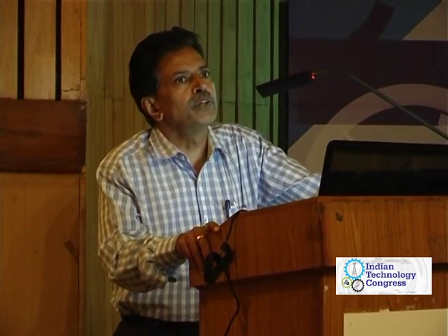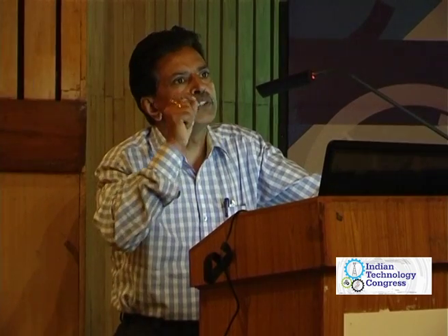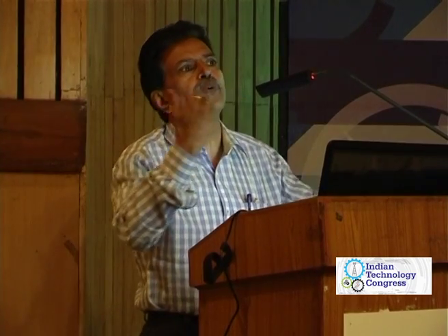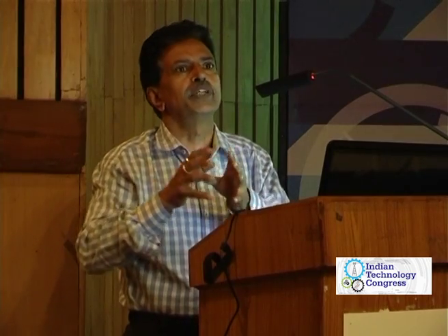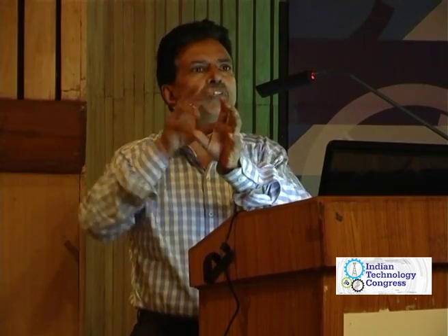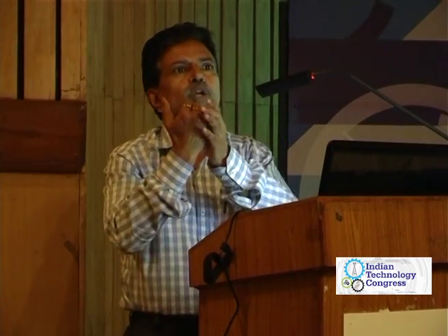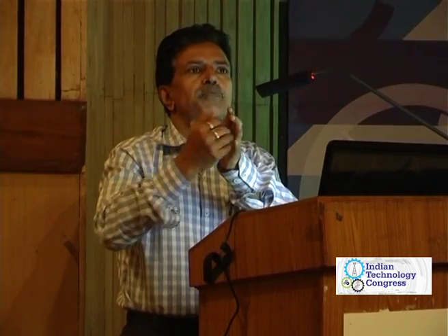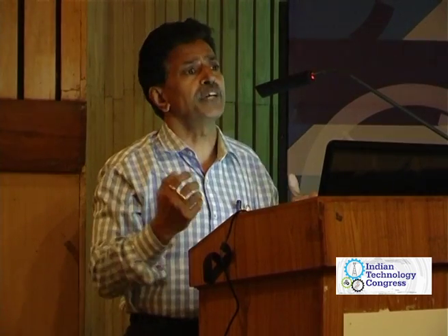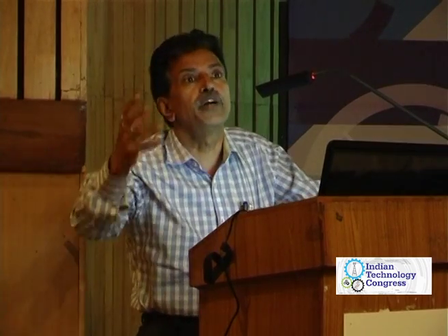The other key issue is the tribological aspects. We do not want the secondary particles to be protruding out of the surface. When you're talking about a piston on which you have a sealant, on which you have the oil, the problem is there's going to be a wearing out of your sealant because of the protruding particles. So that's a real challenge, and it needs to be addressed when we're talking about the end component.